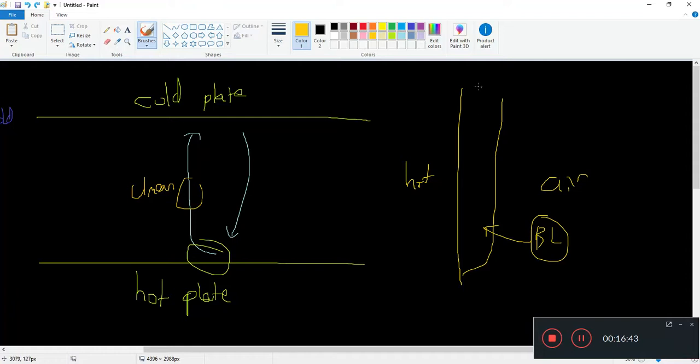Of course, for this case we'll need to pay a little bit more attention, because there is a friction velocity there as well. You might need to take that into account. The friction velocity, which is based on the wall shear stress, will be minimal because there is no mean flow to stop.